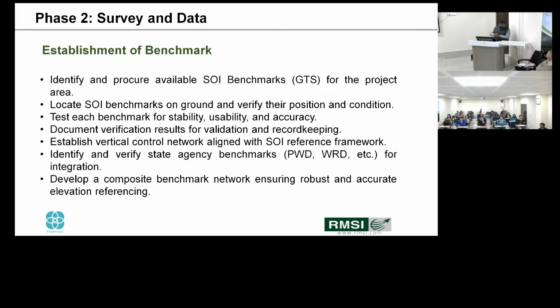So when you use that, you know the concept of ellipsoid and geoid, because this mathematical model considers earth as a proper shape, but earth is not having a proper shape. There is an elevation difference and it is an irregular shape. So whenever you are doing a large area project, to bring the data to match with the ground, we need to have benchmarks.